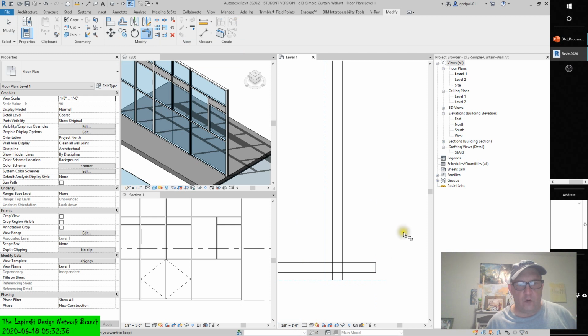Select the second line of wall to trim to extend. Click on the part you want to keep. Well, it's very difficult to select it. You see how it only used its intersection as a cut plane. So we undo that and cancel out the command.